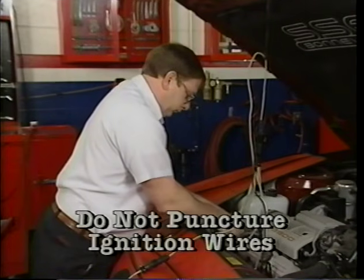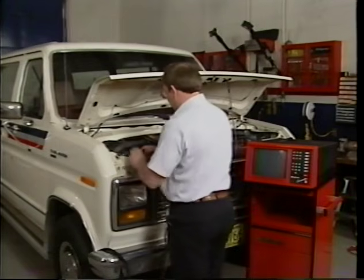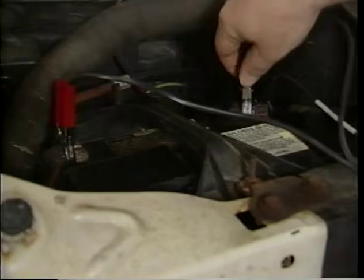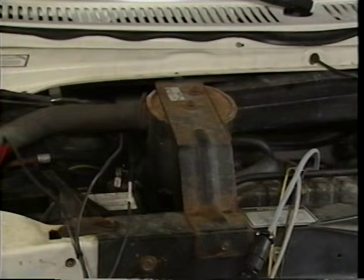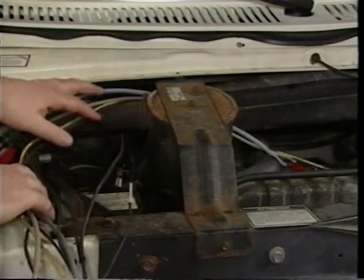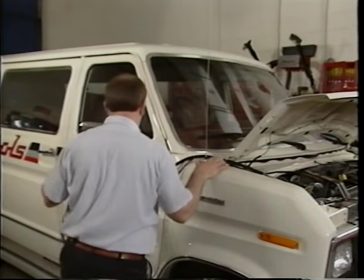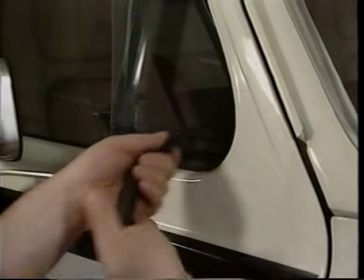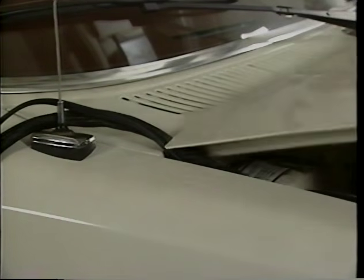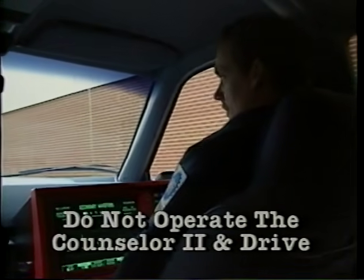Never puncture an ignition wire when you're connecting test equipment. When you're conducting a road test, be sure the Counselor 2 is turned off before connecting the DC power lead to the battery. Be sure the lead set will not come into contact with hot or moving engine parts. Run the lead set out from under the hood and through the passenger side window. Fasten the hood securely, but avoid damaging the lead set. You should never attempt to operate the Counselor 2 and drive the vehicle at the same time.